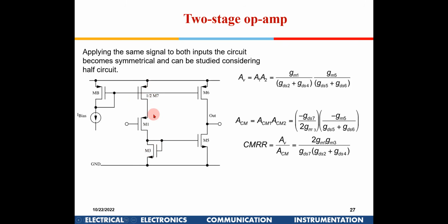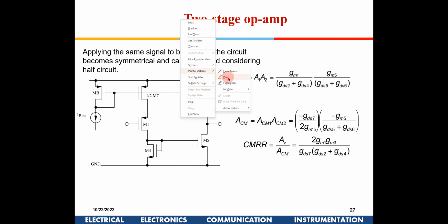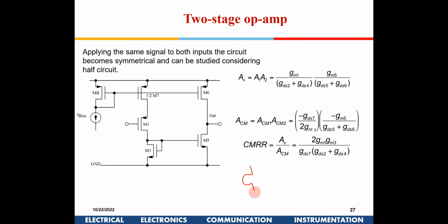Now if you see here the gain of this stage, I am giving a signal here. I have one resistance on top and one resistance on the bottom. So what will be the gain of this for the first stage? It will be just this resistance divided by this resistance, correct? For an NMOS, if it is RD and RS, what is the gain? RD by RS, right? Now it is a PMOS in this particular case, so it will be this resistance divided by this resistance, right? So that is what is done here.